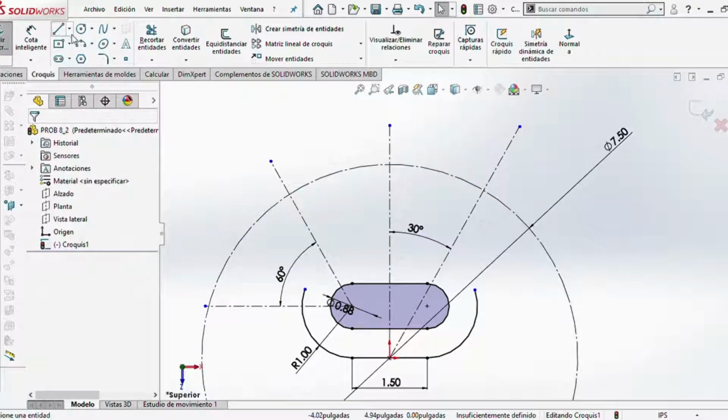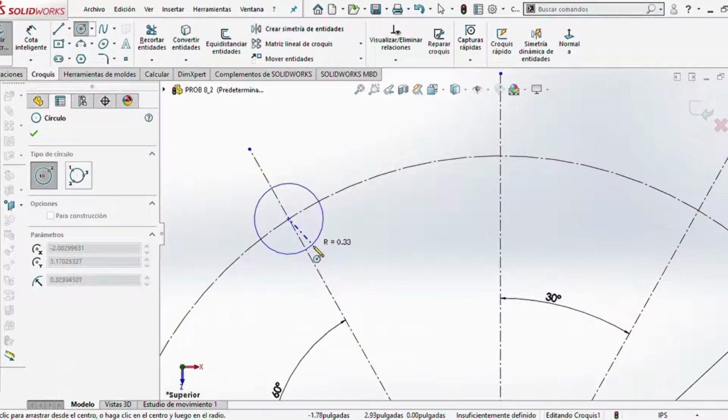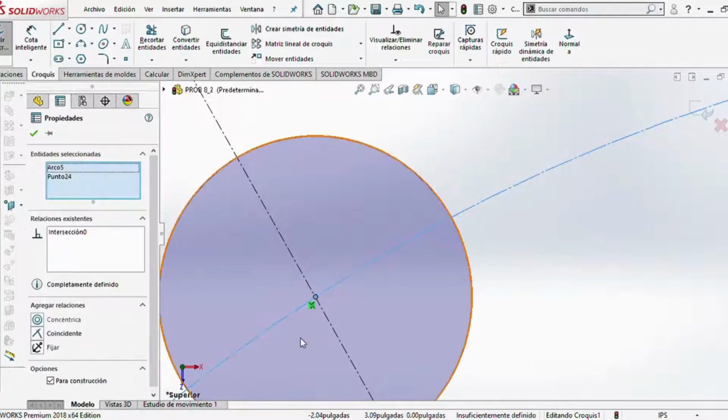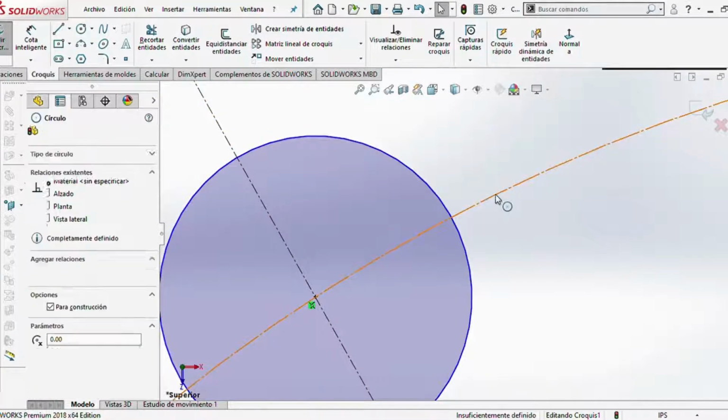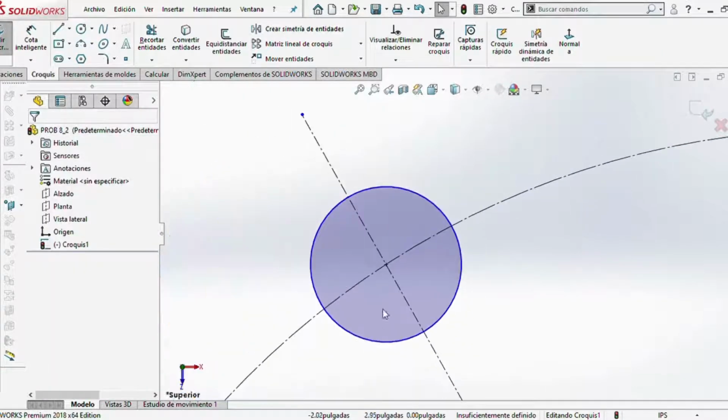There we have it. The second thing that we have to do is to draw a line here where it's coincident. So we already see a coincident in here, but it's between the center of this circle and this vertical line. Now I want another coincident between this bigger circle and the center of the smaller circle. Just coincident.